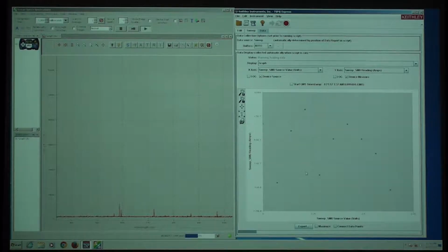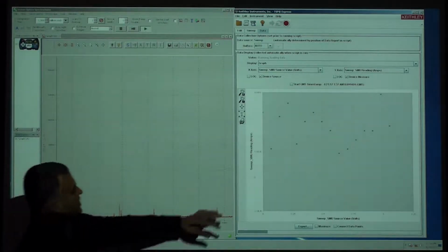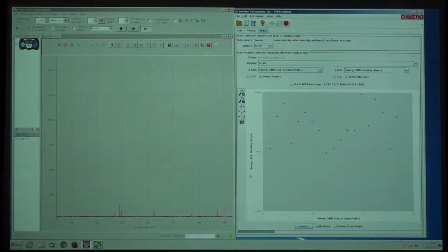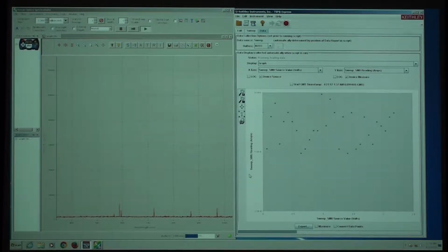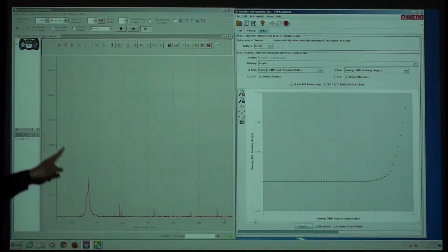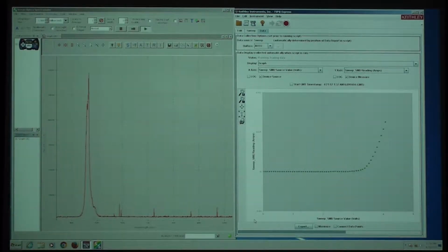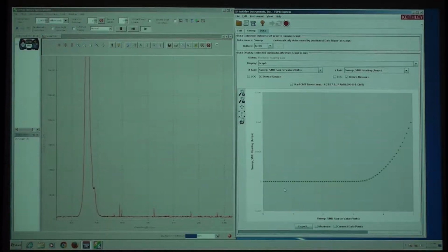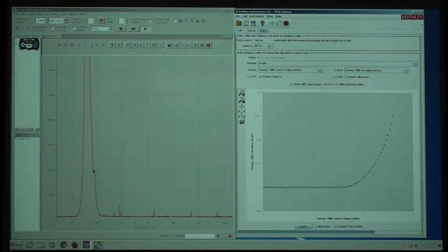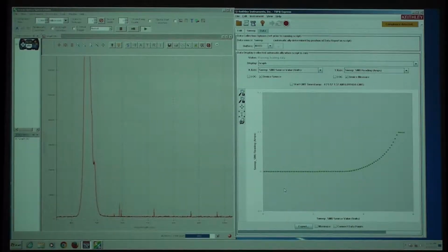So now he's starting a current versus voltage sweep. Currents are very low now, and once it reaches the gap, you will see it exponentially increase. It's very similar to the Schottky diode, except this is GaN, so the gap would be about 3.4. Yeah, there you go. Not much light, or what's going on? Oh, there you see. It's starting to pick up now. This is spontaneous emission at this point. If you were on my side, you would see it with your eyes. You can see that blue spot there. They've tried to create this line. This is spontaneous emission as well.